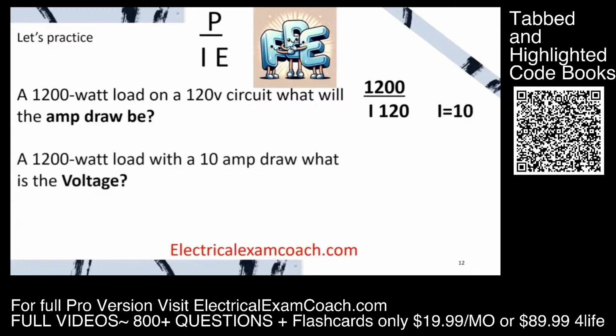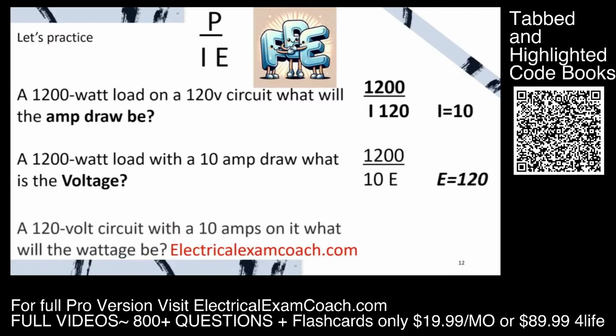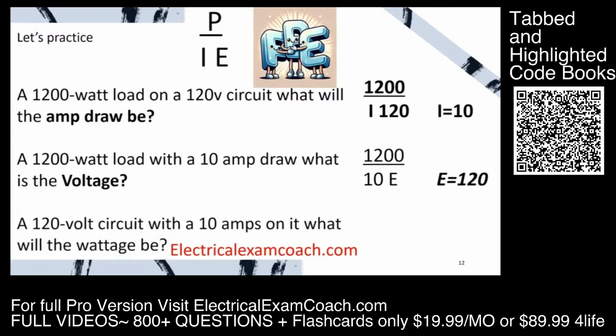We have a 1200 watt load with a 10 amp draw. What is the voltage? Well, let's plug in what we know. We know our wattage and our amperage, and all we're looking for is to solve our voltage. So we divide, and we get 120. And if we have a 120 volt circuit with 10 amps on it, what will the wattage be? That's right, all we have to do is multiply it out. And when we multiply 10 by 120, that equals 1200 watts.